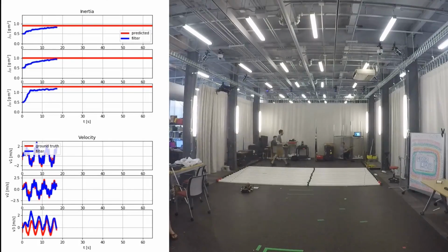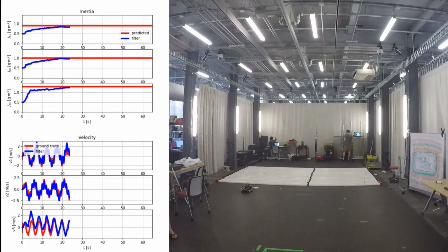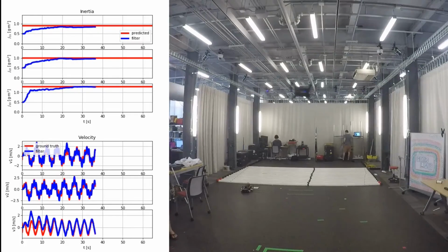Adding rotation dynamics to the UKF allows us to estimate inertial properties of the aircraft and any attached payload using ubiquitous IMU sensors. No cameras or other exteroceptive sensors are required. By carefully modeling the aerodynamic force on the drone in fast forward flight, and at high angular rates, we can both improve the accuracy of these inertial estimates and additionally obtain accurate wind speed velocity estimates. And these speed estimates don't depend on cameras or GPS.